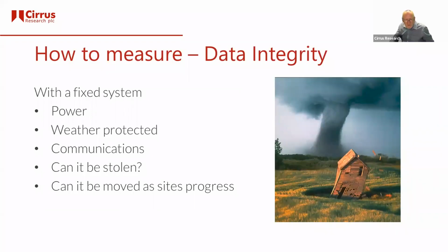So we've got a system there, and you're putting it in there. What else do we need to think about? It's on the boundary, it's going to be fixed. Obviously, it doesn't want to be loose. You don't want any flapping cables. You want to tie them down so that you're not getting any noise from any of the equipment. You just want to measure the sound that's actually there.